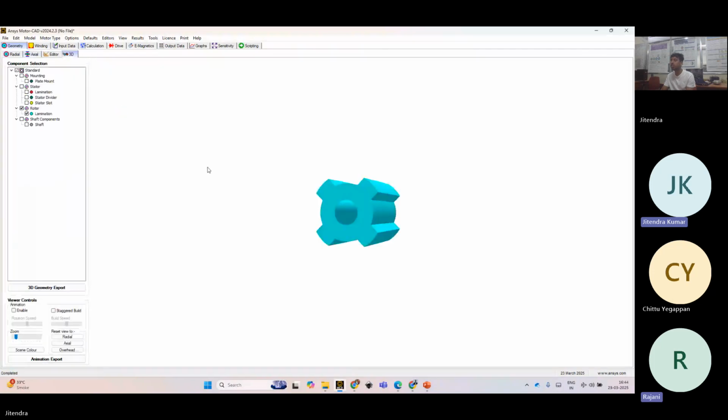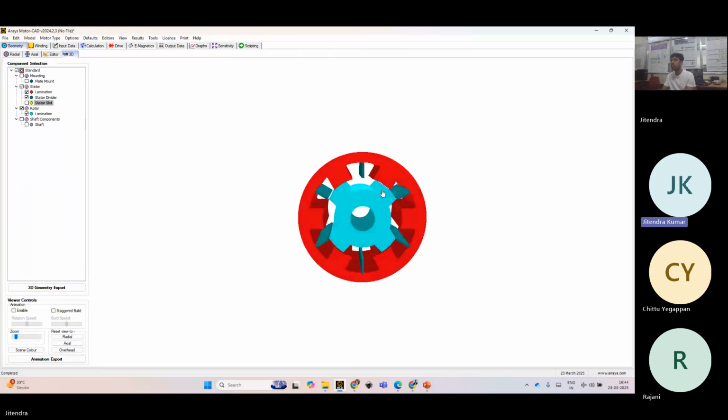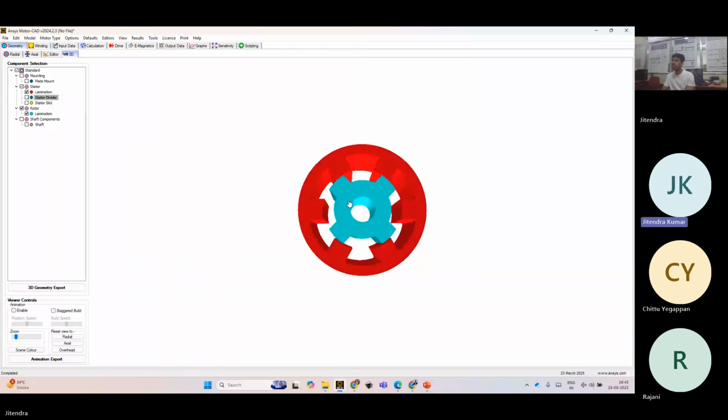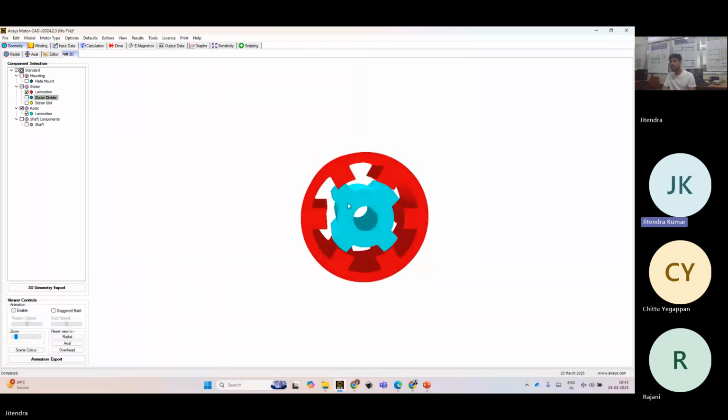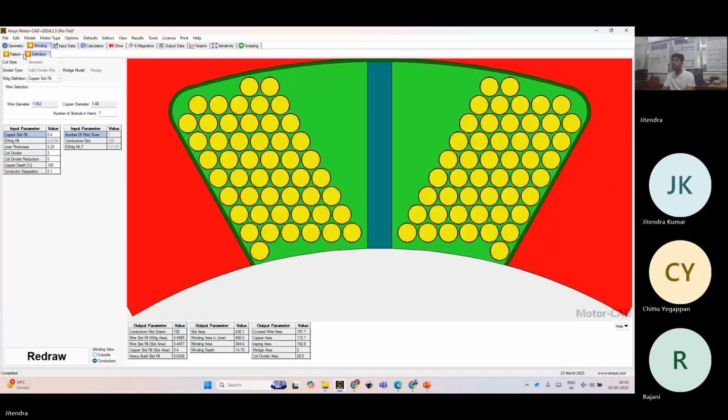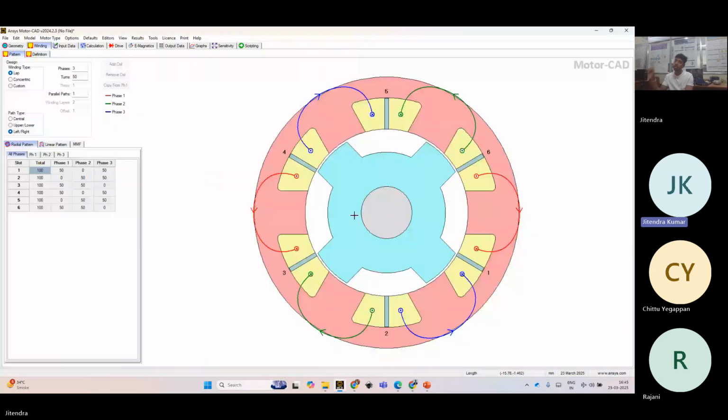So in 3D, this is 90, and this is how the rotor poles are designed. This is the protruded part, and this is how the stators are there. You can see that at this particular instant, all the poles are partially aligned, isn't it? When they rotate, they will either align or unalign. And the winding has been done in this fashion, concentrated winding, around a tooth.